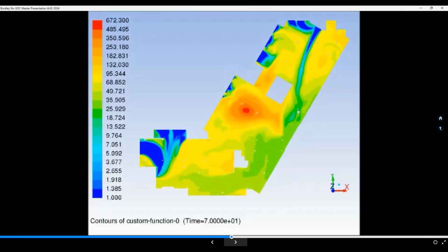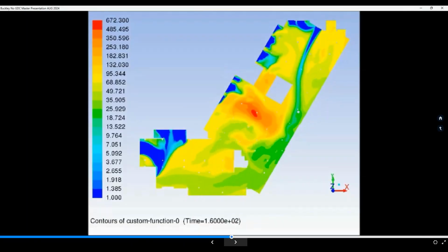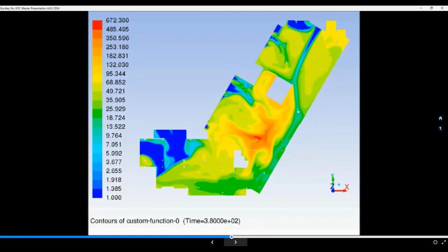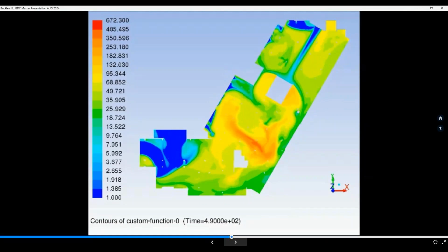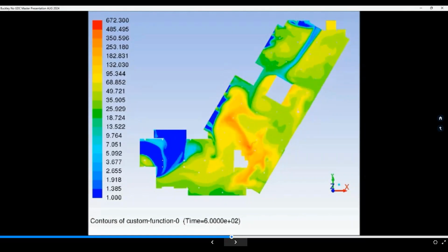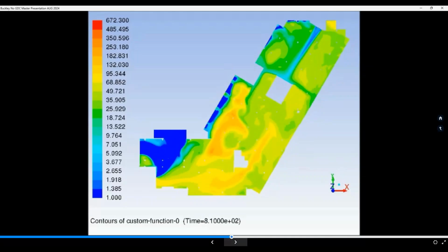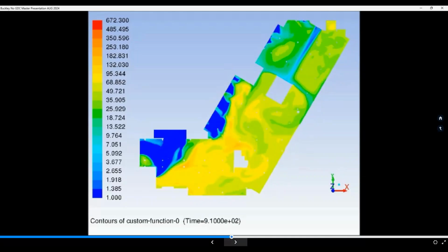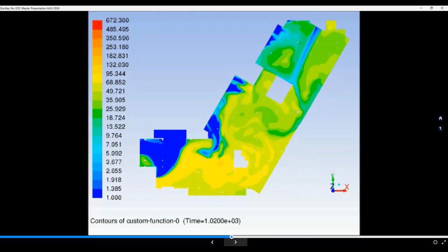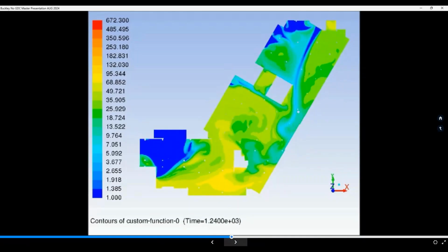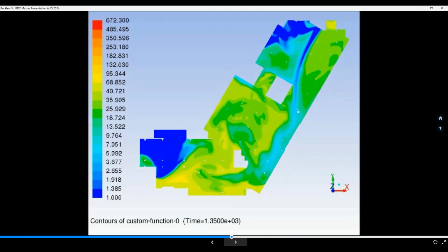So this is a time-lapse video to better illustrate what we're talking about. At the top, you see we have the inlet air pushing in. It hits an obstruction, starts to turn and make its momentum around the obstacle. Down here at the bottom left, where we have the exhaust, you can see we have a great deal of short cycling, because of the location of the louvers and the location of the inlet ramp.